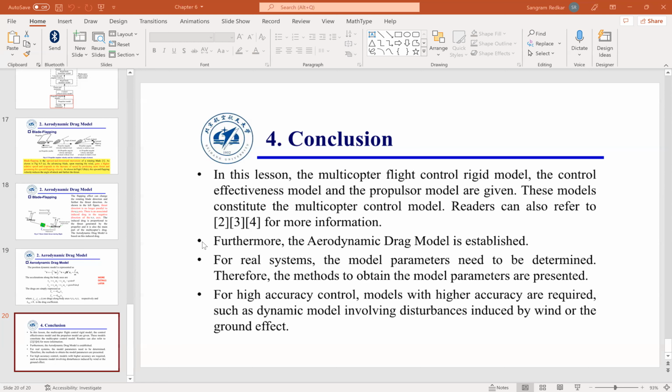On one side, you have Pn north, Pe, Pd down. This is the inertial frame, which is the Earth-centered, Earth-fixed coordinate frame, is equal to. Now what you have is the velocity of the aircraft. Velocity of the aircraft is VB, which is Vx in body frame, Vy in body frame, and Vz in body frame. Are you with me? This is body velocity.